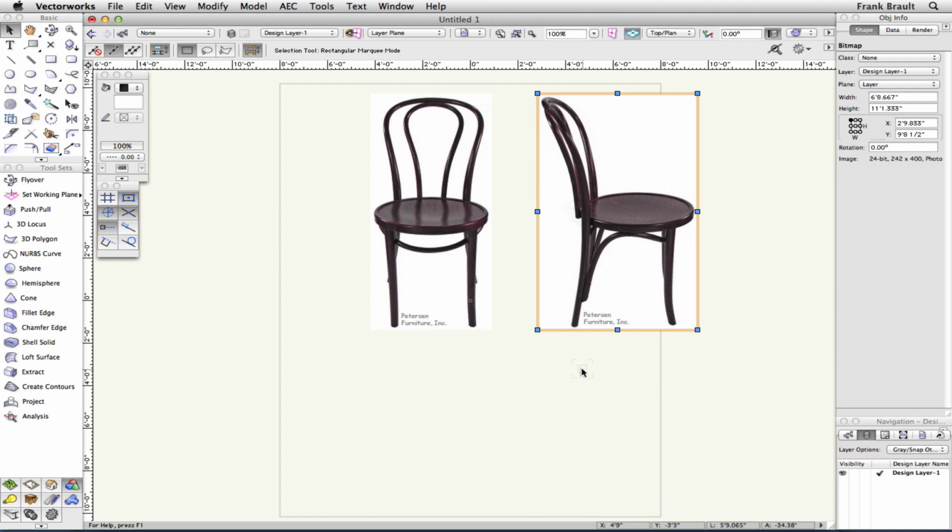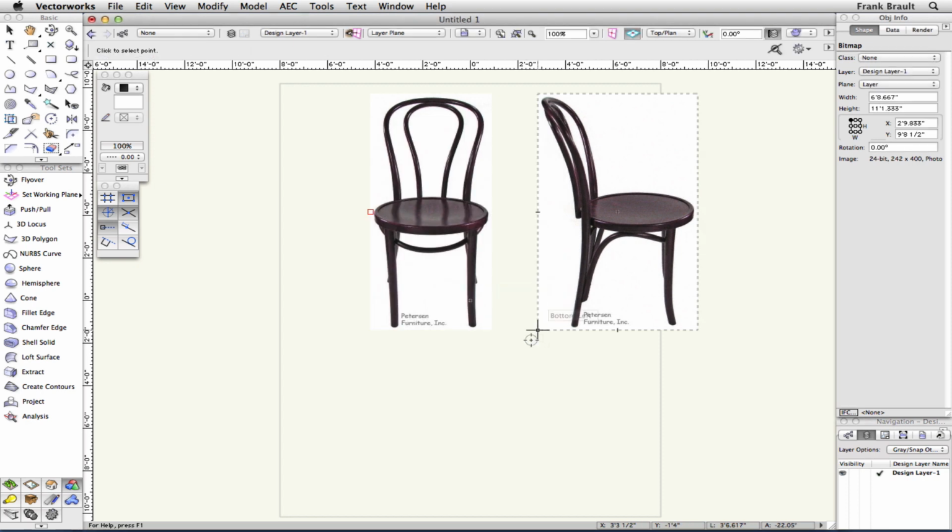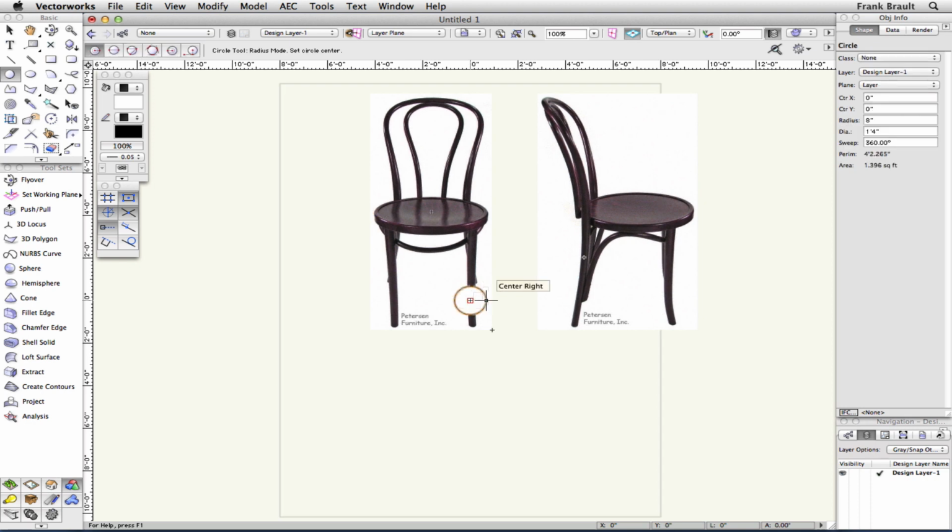Now I'm going to have to scale these as well. So the only size I'm going to work with is the fact that this is going to be an 18-inch circle, and it's going to be 18 inches off the ground. So it's about a square. It could be 16 inches. We can make it 16. So I'm going to start by making the circle. And the radius is going to be, if it's going to be 16, it'll be 8 inches. And I'm going to place it exactly on the center at 0, 0, right there. And that's my center of the chair.